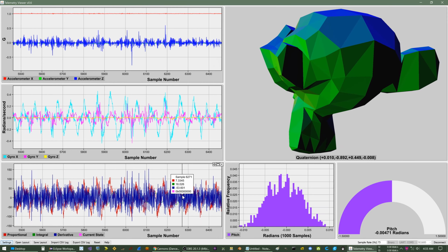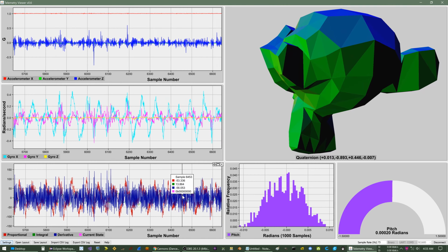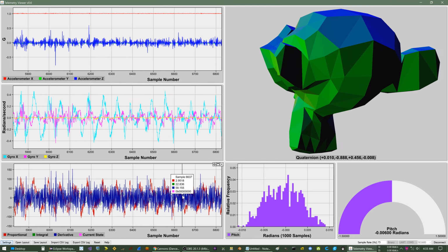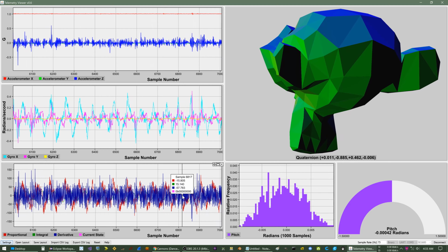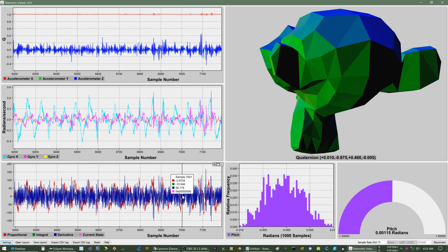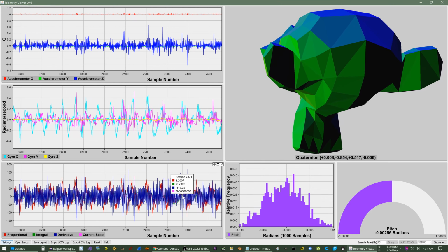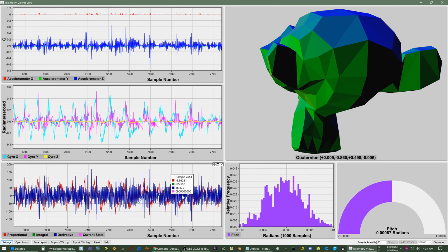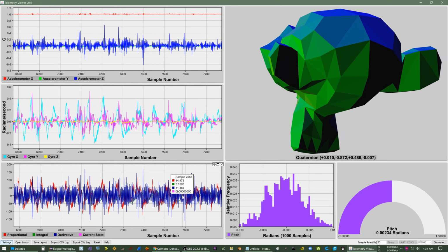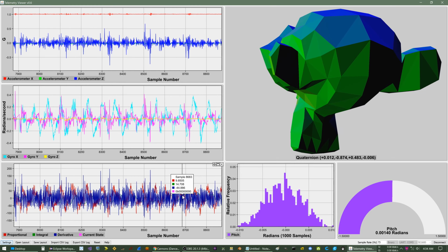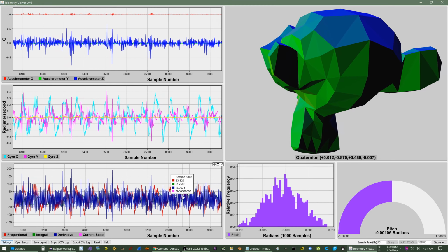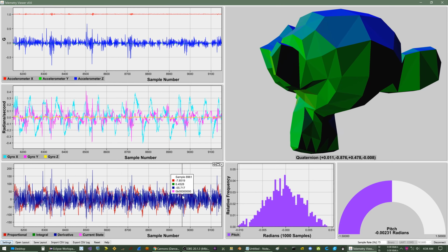In this balancing robot, I have only two boolean values that I'm showing as bitfields. One of them indicates if the robot thinks that it fell over, because if it thinks that it fell over, it will stop powering the motors because it cannot recover. So I have that as a flag. I also have a flag to indicate integral windup. With the PID control loop, the integral part can obviously integrate to a very large value if you have a constant error. And you often want to configure your control loop to limit that so it doesn't just grow infinitely.